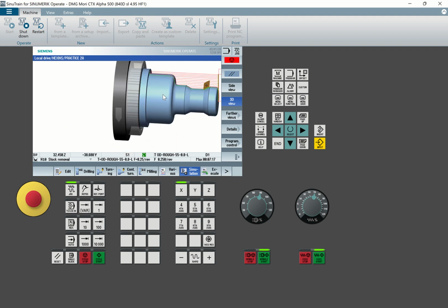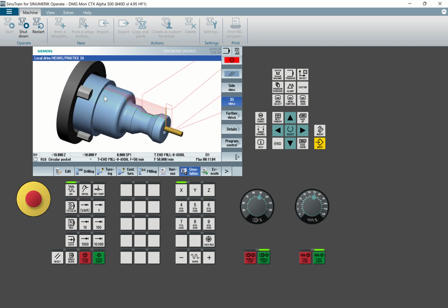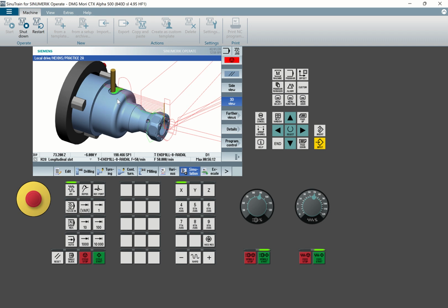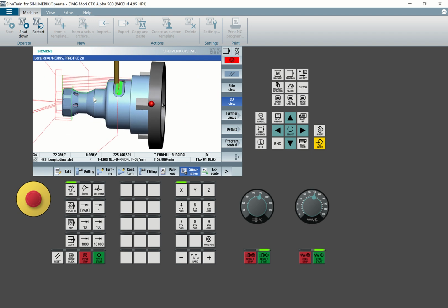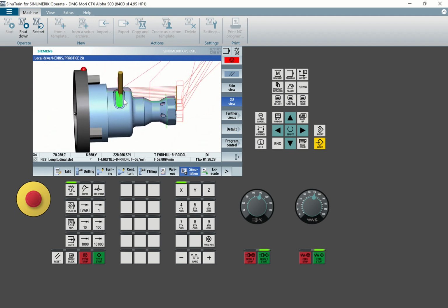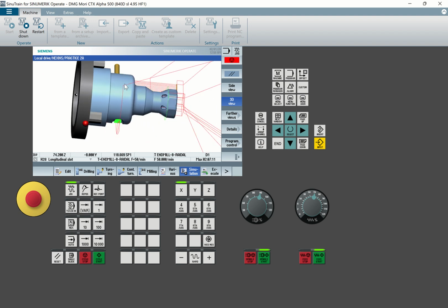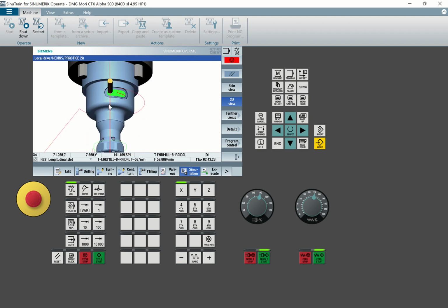You call them the cutting parameters and also the dimensions for your design, because it will affect the output and how you orient the spindle. This spindle, as you see, is oriented depending on the angle you have put when you are programming. So it's very critical when you are programming to understand the orientation of the tool. Let me see how it is going to cut the first slot. As you see, from the first slot it will go to the second slot, then it goes to the third slot, then it comes back to the pocket on the surface.